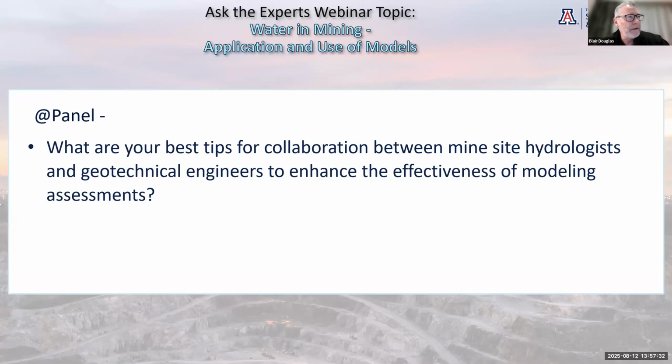So being able to, like I said earlier, if your error in your hydrogeology is greater than your uncertainty, so your sensitivity to pore pressures, you've got to do some work. And that's the first thing I always look at: what is that sensitivity? What is the failure mechanism? What do I know about the hydrogeology and how erroneous could it be, and how does that then need to be improved to get to a level of confidence?